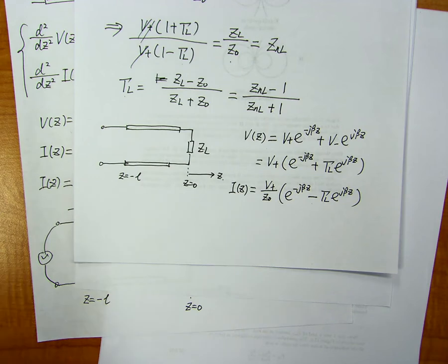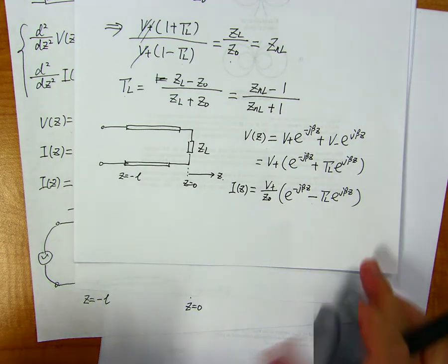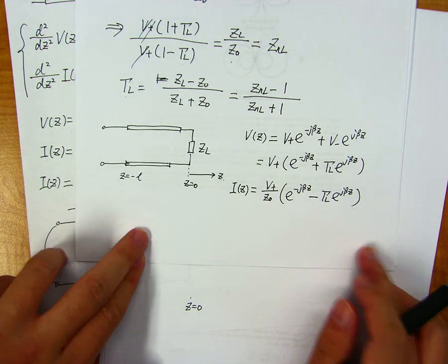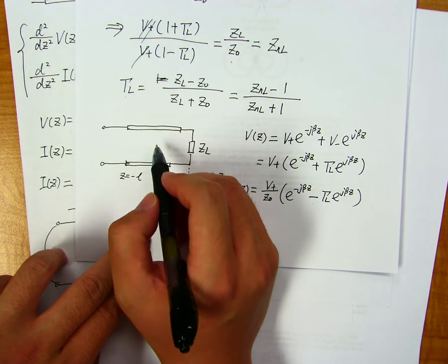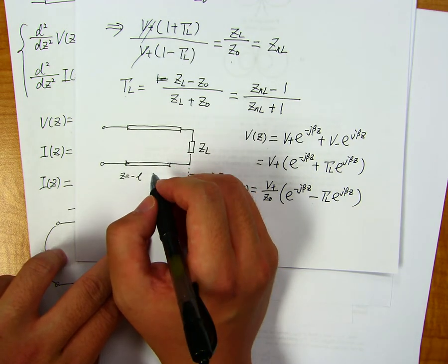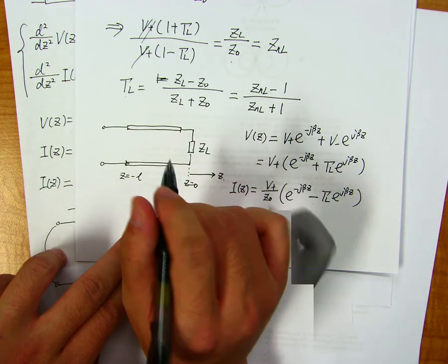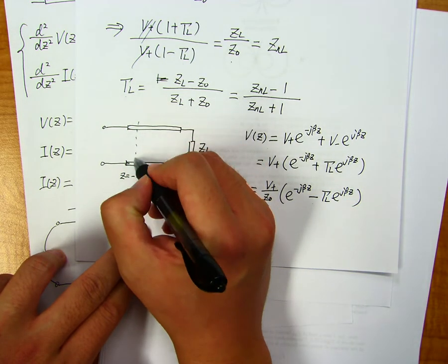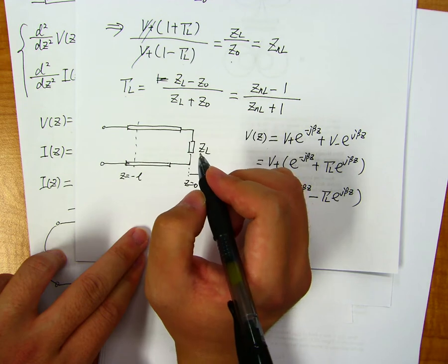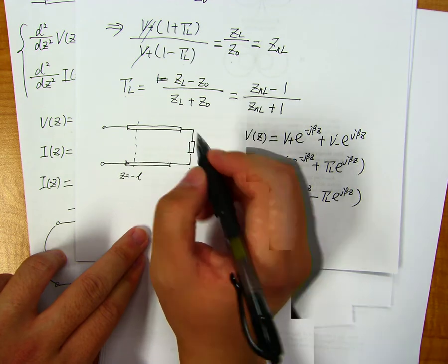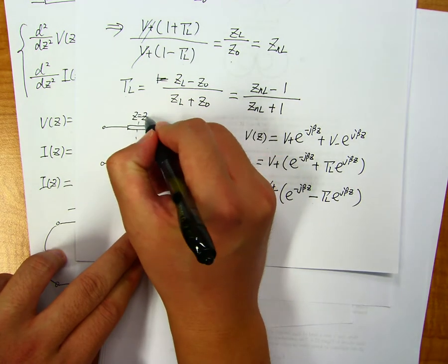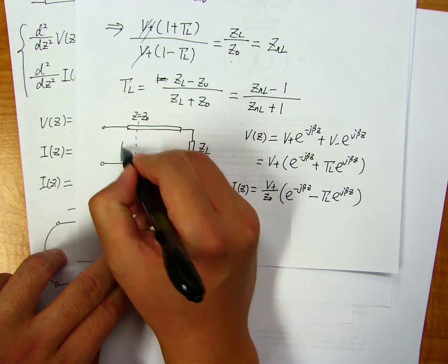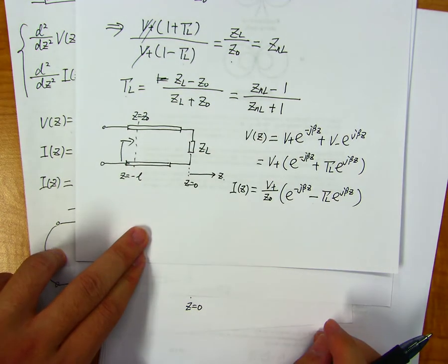Okay. So, good. So we have the expression for the voltage along this transmission line as well as the current along this transmission line. Okay? So now if I specify the z coordinate, let's say z equals z naught, then we can define an input impedance at this point, actually at an arbitrary point. Okay?